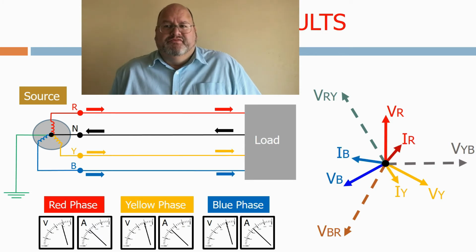The magnitude of the three-phase currents depends on the impedance of the loads and cables connected to the source, so these continuously vary. The angle between the current and voltage vectors also depends on the connected impedance, and again is continuously changing.